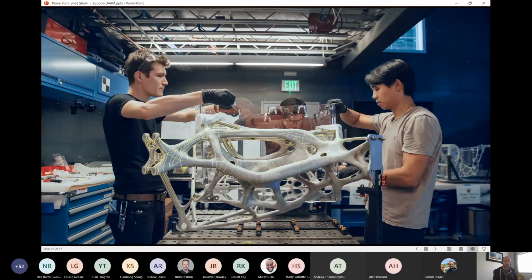So my background is one of tool making, and quite often, many of the components and products that we have were never simply just designed and made as the component, if you like. You have the overall component that you want to end up with, and then you design and make all of the necessary tooling required to make that component. So in this example, 3D printing or additive manufacture was used to print the pattern that was then going into a sand mold, and then also used to actually print some of the sand for the casting process. So to present some of the cavity and core halves for that sand casting.